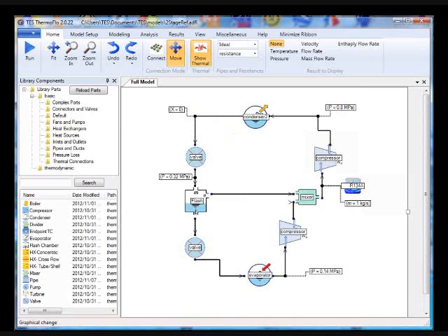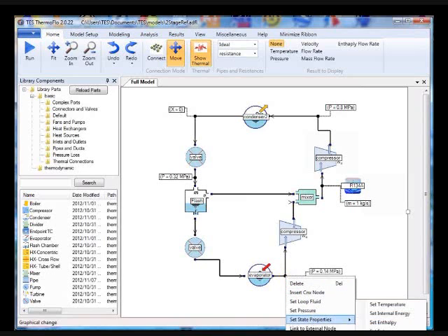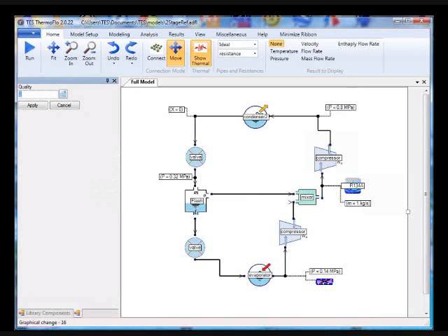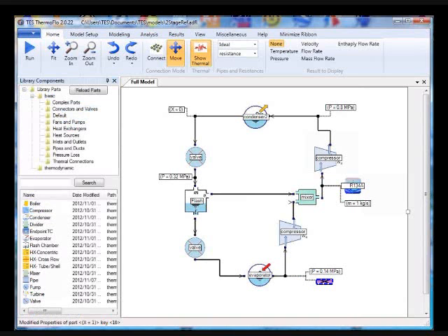And also at the bottom, we have an evaporator. If it's ideal, it's going to come out as a saturated vapor. So we go there and we set that quality equal to 1. That's about all you need to do. You can solve the problem. No need to look up steam tables, refrigerant tables, and iterations and all that.